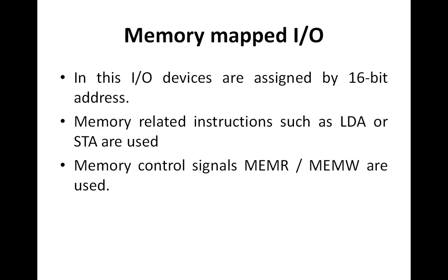One more change: in case of peripheral mapped input output, we used to generate the control signals, that is the input output read signal and the input output write signal. But in case of memory mapped input output, we have to generate the memory read signal as well as the memory write signal.